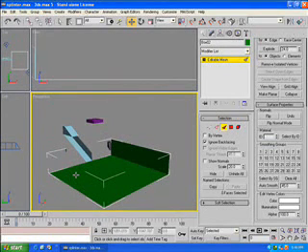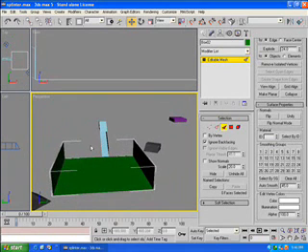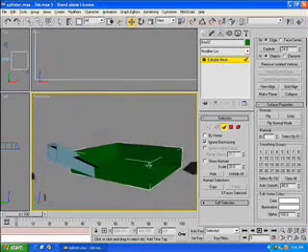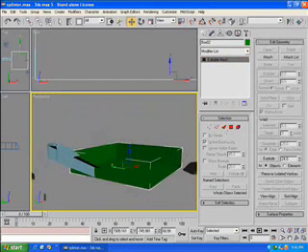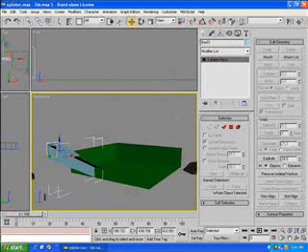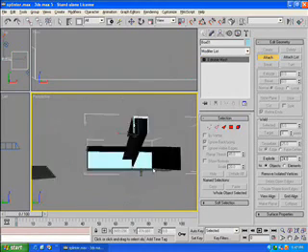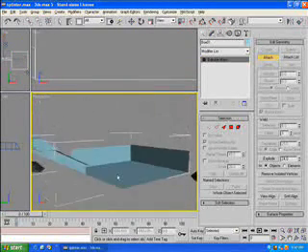Now we need to actually create faces that will make up this wall here. We deleted that wall because we needed a way to get into this room. Now we need to connect and attach that wall to our ramp here. So we're going to go out of face edit mode, select our ramp here, and we're going to want to, under edit geometry, click on attach, and then we're going to want to attach box number 2 to that. So now we've merged the entire thing here.